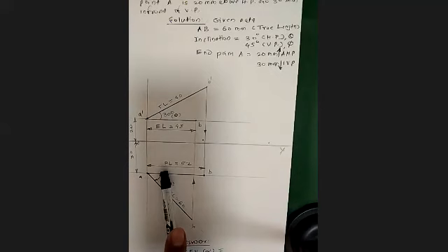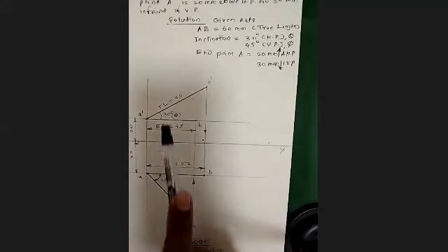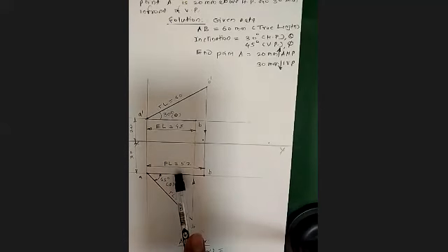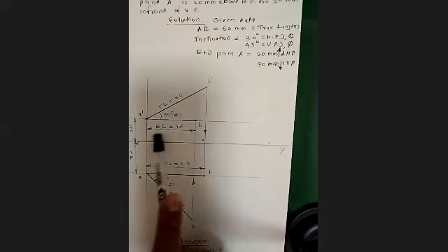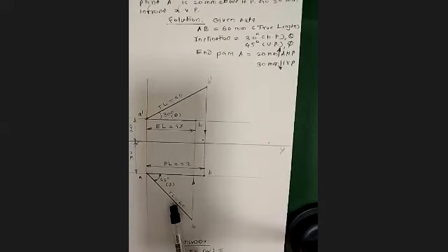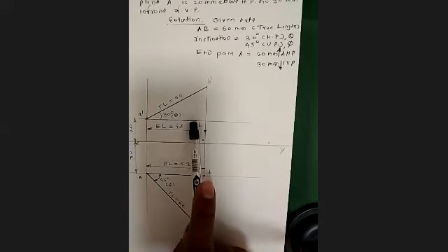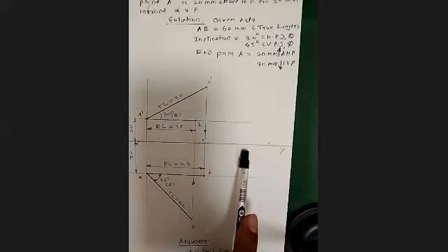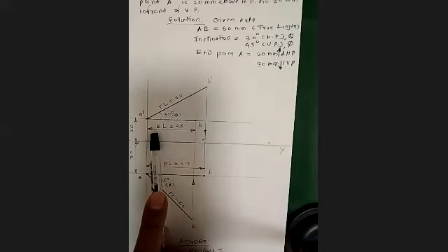Okay, so this case you did when we took the problem of a line inclined to one plane only. Okay, so for this front view, this is the top view. Now for this top view, this is going to be the front view, meaning for this true length top view, the true length front view will be the line parallel to XY line, or it is nothing but the front view length, or alternately we say it's an elevation length, and in short it is written as EL, right?